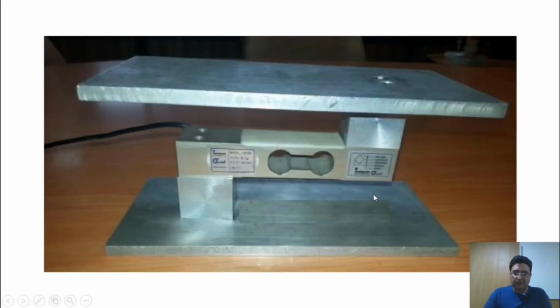And here is an example of installing an A220 load cell, where, as I mentioned, a plate is placed above the load cell, and this top plate is connected by a load button to the load cell itself. The bottom plate is the same way, meaning the plate beneath the load cell is also connected to the load cell by a load button. This setup is what we call a single point load cell. This means that no matter where you apply force on this plate, it measures the total weight for you as a single value.